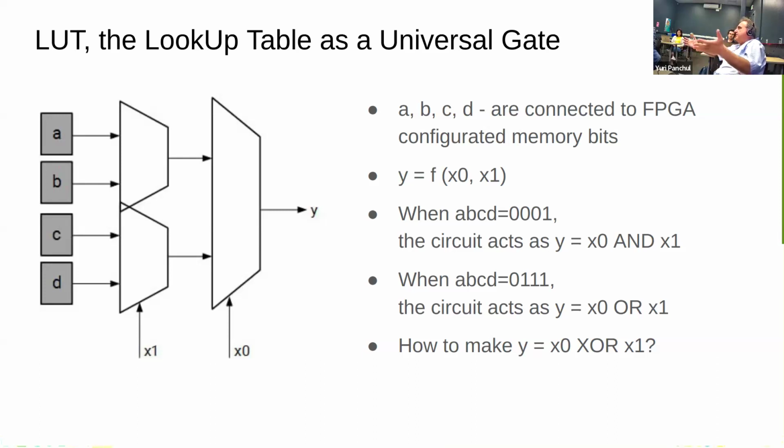So an emulator is halfway between simulation and manufacturing. With a simulator, to simulate loading and booting Linux, you need to spend several days simulating this Verilog. To boot Linux on a manufactured device takes seconds, but with an emulator, it takes a couple of hours.